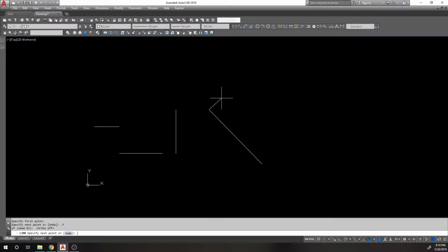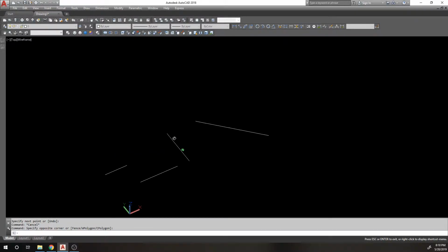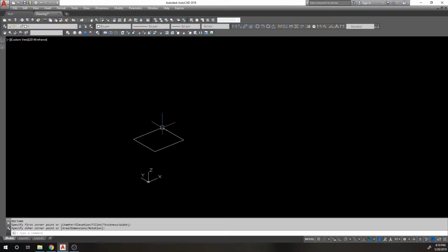Actually, I don't have to because I actually clicked. You can click. Okay? The reason that you would want to use this instead of snap tracking is mainly in 3D. Okay? Let's get to 3D. Let's say I've got a box and I extrude that box.